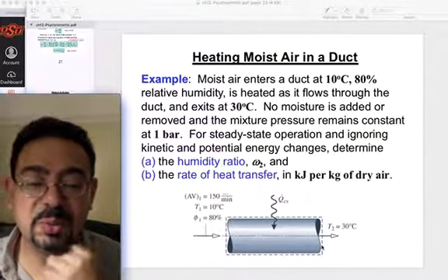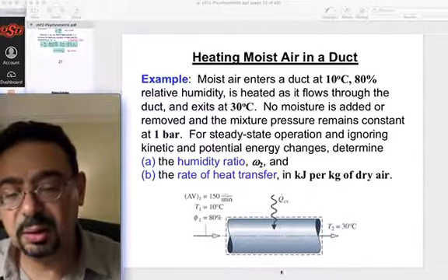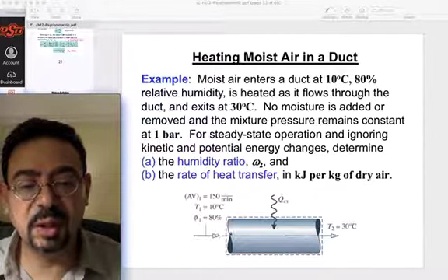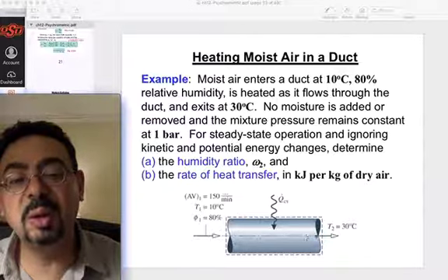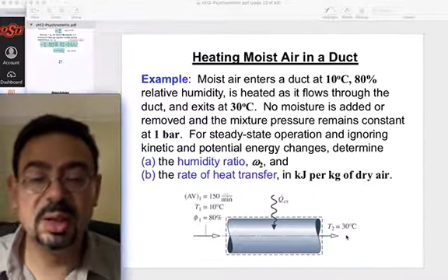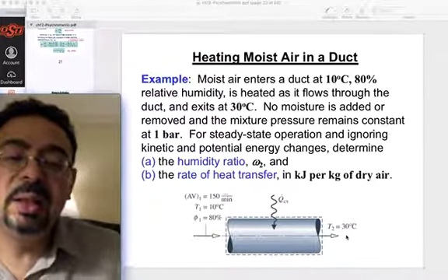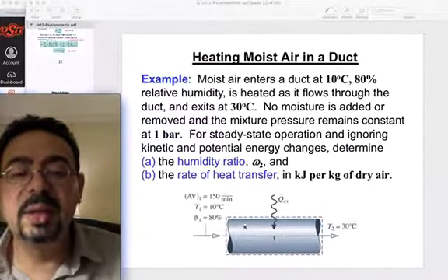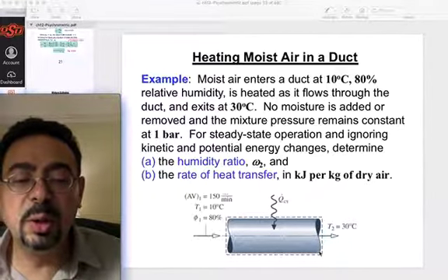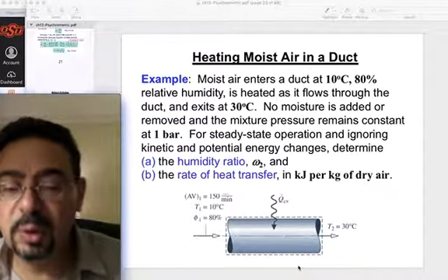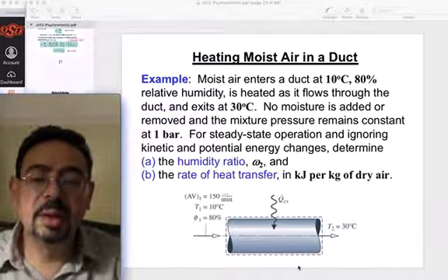So will this always be the case in all problems? Well, the air will, unless you are taking air somehow out. Most of the time, m dot air in equals m dot air out. Now, m dot water in equals m dot water out will not always be the case. When will it be different? If the water is going to condense, leave the vapor state and drop as water droplets that we collect from the floor in a drain. That happens a lot in air conditioning.